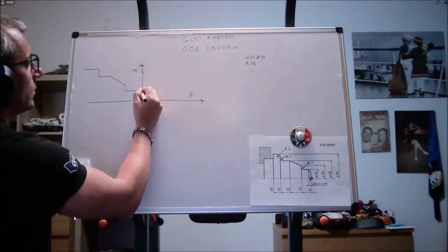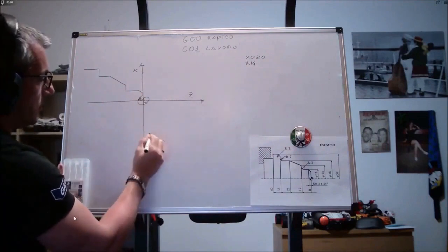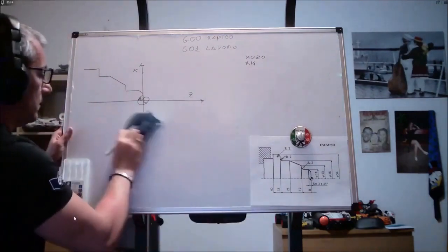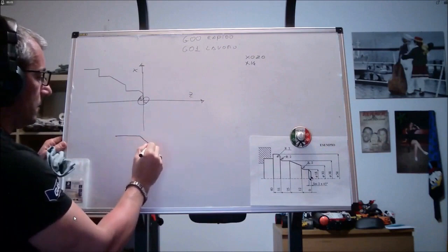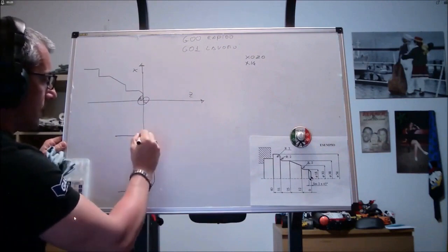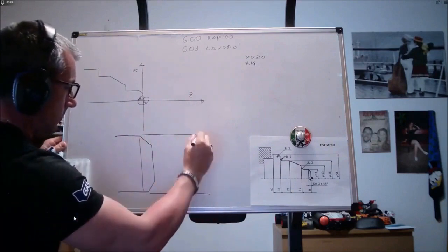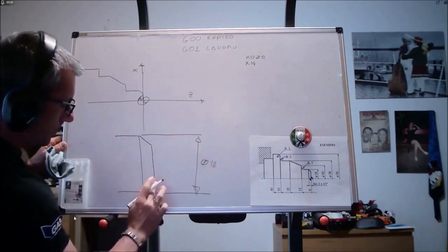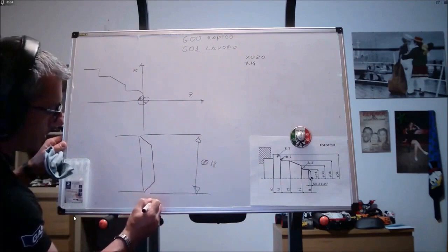So, since we have, let's exaggerate a bit for clarity, a chamfer, which is a transitional edge between two faces of an object. I have never drawn it for you before, but now I will. Imagine a piece made like this. This diameter is 18 millimeters. This distance from here to here is 2 millimeters, but also from here to here is 2 millimeters, and 2 millimeters also from here to here, because the chamfer is 2 millimeters at a 45-degree angle.